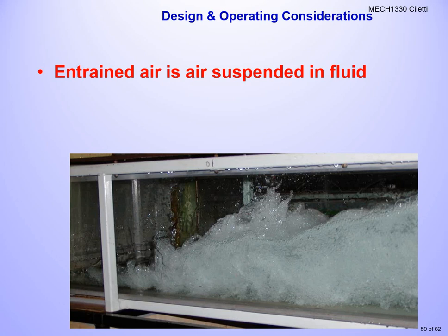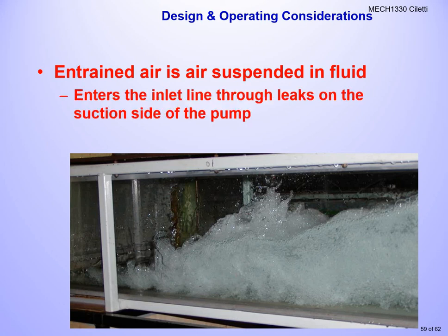We also have entrained air, air that we suspend in the fluid. Think about a bubble in a thermometer or a bubble in a level. That's kind of the same concept. Entrained air enters the inlet line through leaks on the suction side of the pump or things like that. Think of a level that we use in the mechanical class, and it's got that little bubble in the fluid. That's kind of like entrained air. It's trapped in the line.